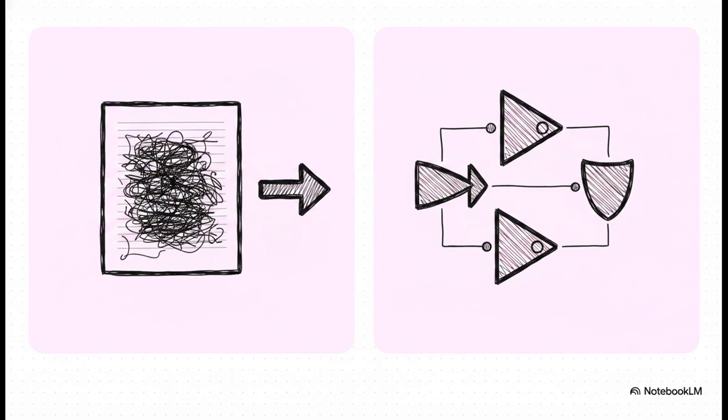And this brilliantly illustrates step 4, logic synthesis. It is this massive leap from software into actual hardware. We use synthesis tools like Synopsys Design Compiler to completely convert our RTL code into a gate-level netlist. The software literally transforms our counter code into a network of physical building blocks. These are your standard cells, like AND gates, OR gates, and flip-flops. So the code, it's gone. We have an actual hardware schematic now.